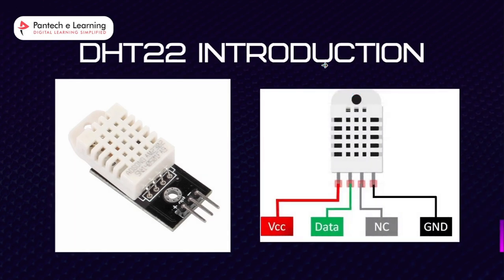So coming to this, the DHT22 is an inexpensive sensor which measures relative humidity and temperature. It provides a calibrated digital output with a one-wire protocol. It measures temperature and humidity with higher accuracy and supports a wider range as compared to DHT11. So DHT sensors are pre-calibrated actually. We can directly connect them with our STM32 board to obtain sensor output readings. They are internally composed of a humidity sensing sensor and a thermistor. So these two components measure humidity and temperature respectively.